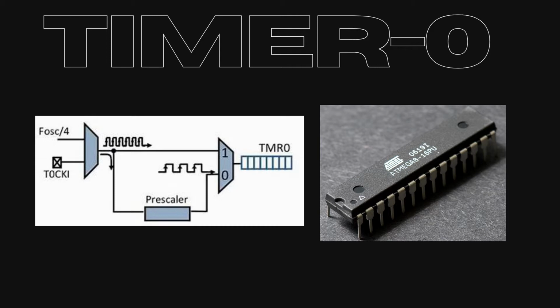The second is Timer0 delay using interrupt. In most PIC devices, the Timer0 module is an 8-bit timer or counter. When Timer0 overflows, it can also cause an interrupt. Based on Timer0 interrupt delay, this project will make a flashing light emitting diode or LED.